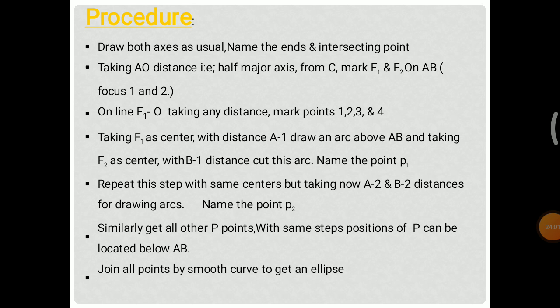And next to it, all the defined lines and other curves can be drawn with the 2H pencil only. That is, with the thin line only we draw those. Apart from that, the ellipse section is drawn with the HB pencil only. The curve is drawn with the HB pencil only. So these are the general procedure for drawing by the arcs of circles method.